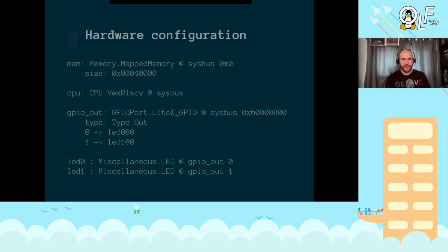But if you interact and use your CPU instructions to read and write to this location, you're writing to the emulated hardware and putting the state of what you want the LEDs to be into this location. So what we were doing in that assembly level program that we just looked at, we were reading and writing a byte to this memory location, and that byte was being then taken by the simulated hardware and put out onto the LEDs. This is showing how to make a connection.